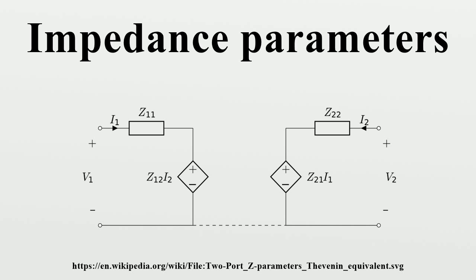Two-port networks. The Z parameter matrix for the two-port network is probably the most common. In this case, the relationship between the port currents, port voltages and the Z parameter matrix is given by, where for the general case of an n-port network, impedance relations. The input impedance of a two-port network is given by, where ZL is the impedance of the load connected to port 2. Similarly, the output impedance is given by, where ZS is the impedance of the source connected to port 1.